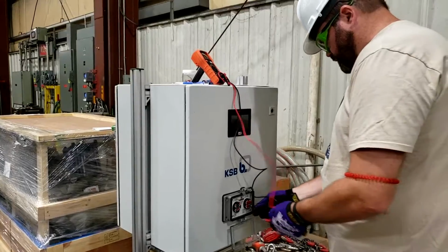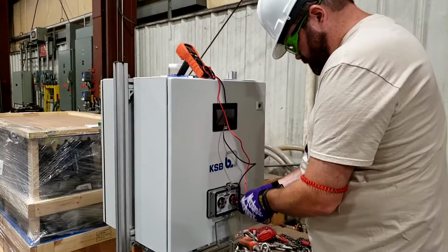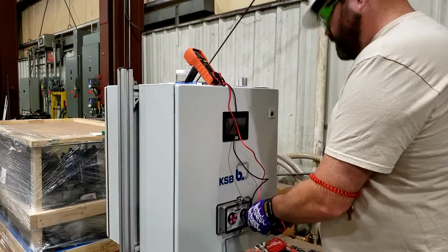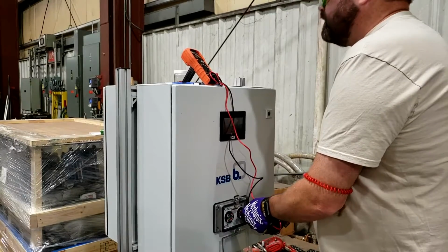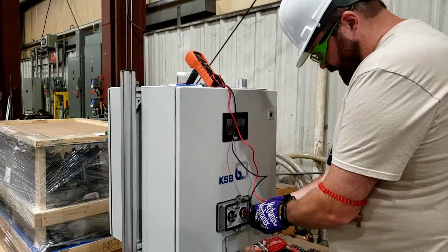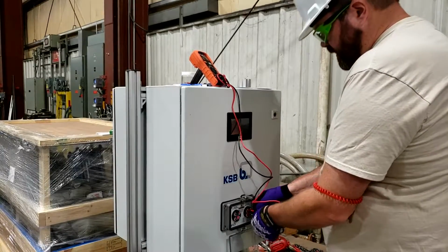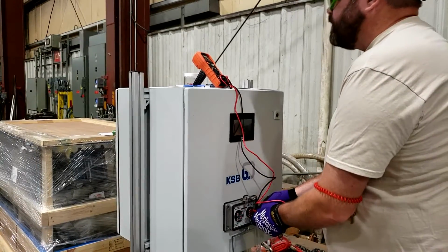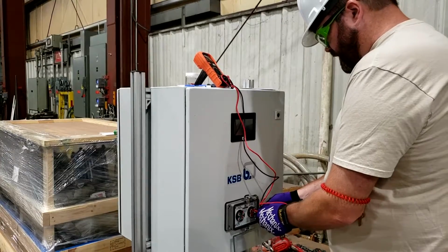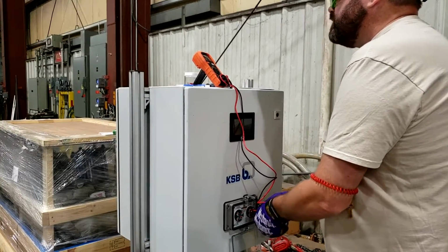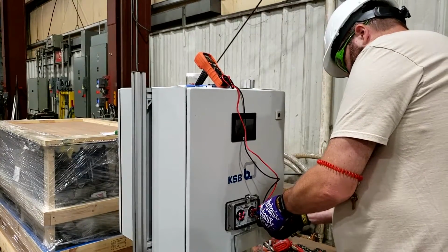You'll communicate out loud that the power is confirmed secure. Open the door to the voltage test station, power on the multimeter, turn to the voltage setting. Using the multimeter, you'll conduct 6 tests: ground to leg 1, ground to leg 2, ground to leg 3, leg 1 to leg 2, leg 1 to leg 3, leg 2 to leg 3.